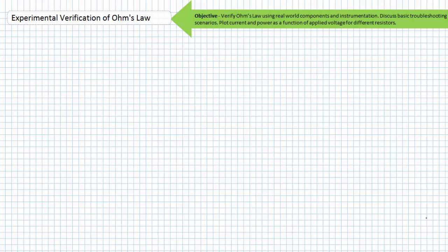smell the air. The resistor I ignited at the beginning of this activity has a uniquely identifiable smell. If you smell that smell, the problem is electrical in nature. Oil subjected to intense heat undergoes thermal degradation and changes odor. Know the difference. Fresh oil should smell sweet. Thermally degraded oil smells like a campfire.